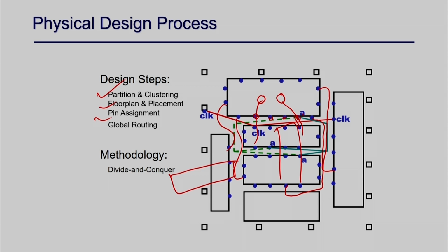For example, you want to make the connection from this node to this node, so you decide that this will go through this path, or in some scenarios it might go through this path also, because of some reasons. That is what is called routing. You know that you have to make a connection from this port to this port, and you can understand that for a bigger layout there may be multiple such possibilities, and you have to make this connection exact. Which part of the channel it should go through, that you have to decide. That is what is called global routing.